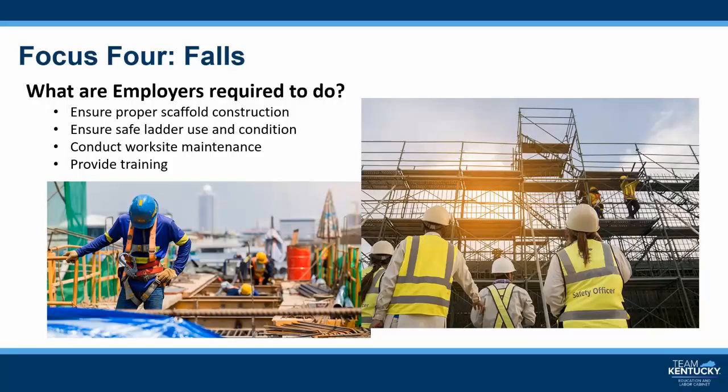Poor worksite maintenance can lead to clutter and debris on a construction site, creating additional slip, trip, and fall hazards. Poor maintenance of ladders, scaffolds, and fall protection equipment can also lead to serious injuries. Employers are required to keep work sites free of form and scrap lumber with protruding nails and other waste and trash, including combustible debris. Employers are also required to provide training.